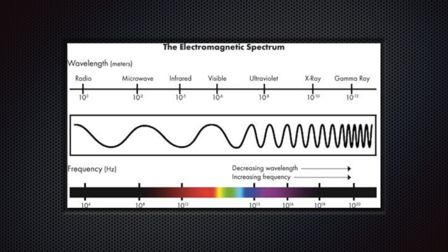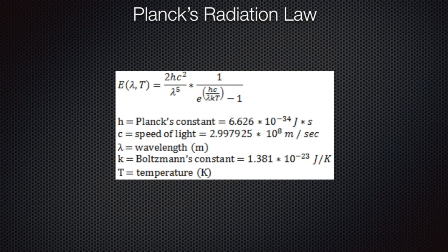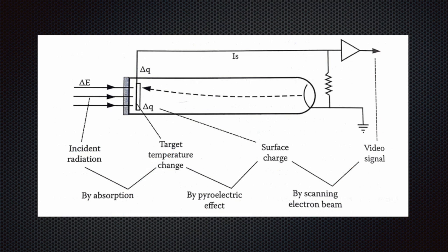The main physical phenomenon by which infrared thermography operates is the emission of electromagnetic radiation. All temperatures above absolute zero will cause matter to emit electromagnetic radiation, and the amount and distribution over the wavelength spectrum correlates directly to the temperature of an object. Since the maximum amplitude of the energy transmitted at a given frequency is given by its temperature and surface emissivity, it is only possible to know the gradient of the surface temperature for an object without the surface emissivity value of that object. Thus, to obtain temperature values, infrared thermographs require the use of black body objects, materials with constant emissivity values for a range of spectrums, for calibration.